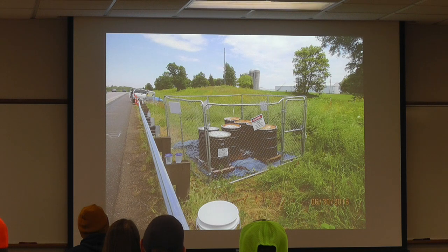So, if using steel shot, you won't have a lot of waste. The only waste that you end up with is the rust, the paint chips, anything that is non-ferrous as far as the steel shot itself goes back into the machine, like I said, and then you've got the waste dumps. So this is a typical flyover interstate bridge over, say, I-35. And you've got 7 barrels of waste. Not bad, actually pretty good.